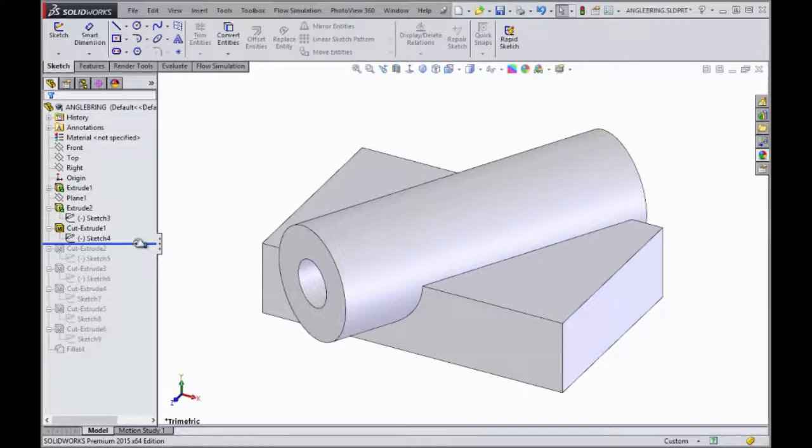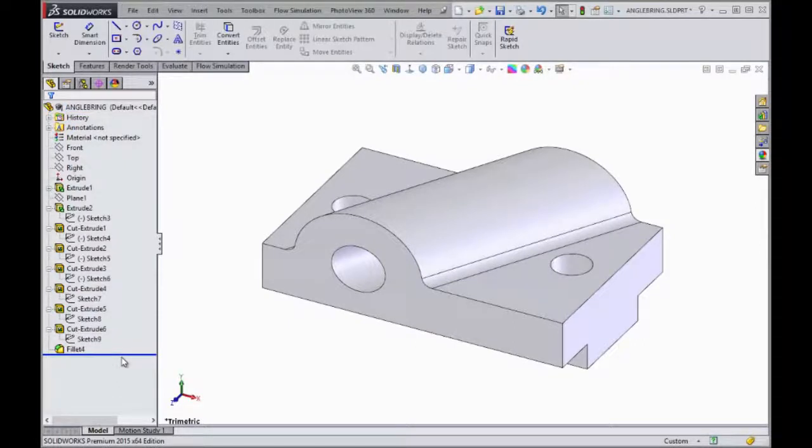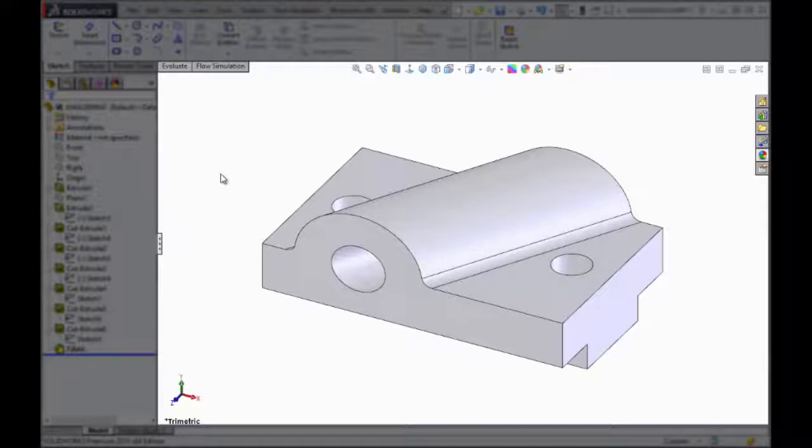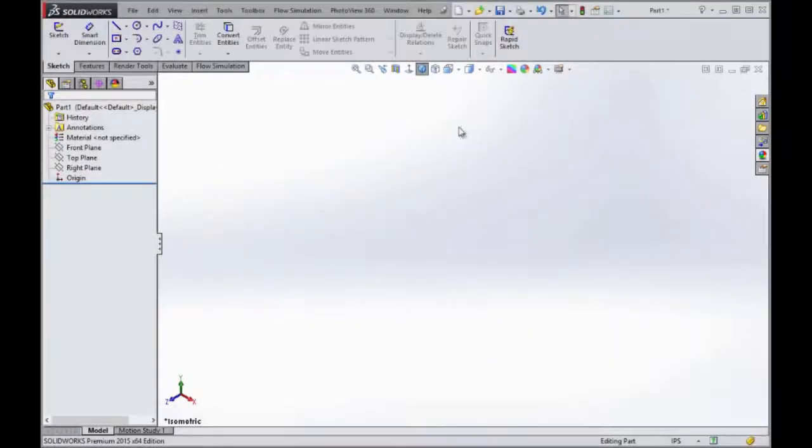As I said earlier, SOLIDWORKS parts consist of various 3D features building upon one another to make a 3D part. These can be either applied features, which are applied to existing solid geometry, or sketched features, which utilize sketch geometry to define their profile, direction, and size. The graphics area is where you'll create and view sketch geometry.